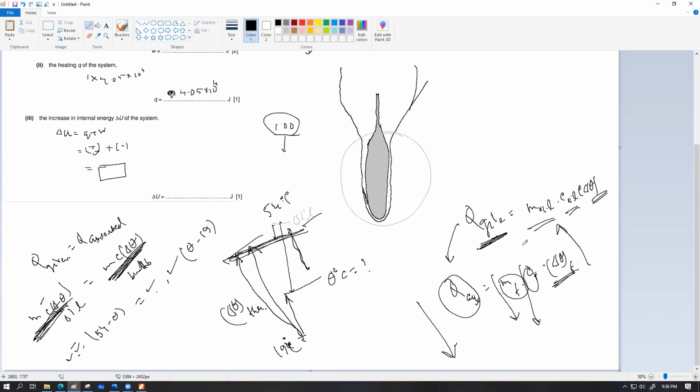We have to measure the temperature at equilibrium, and to achieve that either of these two, or maybe both of these two, has to be extremely small. So that's where the thermocouple thermometer comes in, because the hot junction of a thermocouple thermometer can be designed to be extremely small, like a pinch of metal, the heads of two wires soldered together. So you put that junction there, and once the final temperature is reached immediately, you can take the temperature.